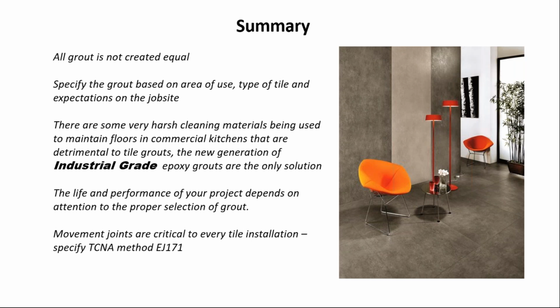The life and performance of your project depends upon the attention to the proper selection of grout, and then making sure that the movement joints are properly installed per EJ 171 in the TCNA handbook. Like I said at the very beginning of this presentation, the grout is about 5% of the cost of the job, and yet it's about 95% of our problems. By selecting the right grout, the right color, and the right installation, we can eliminate a lot of problems from the job.